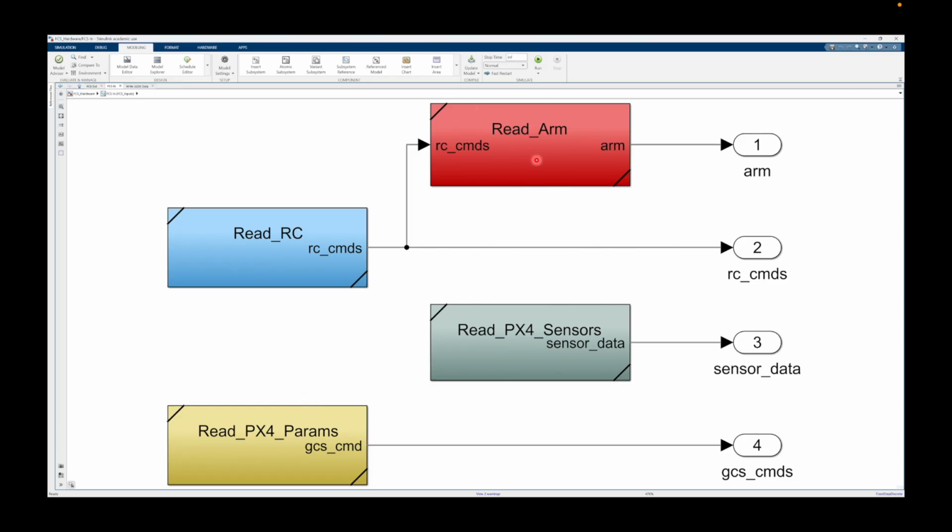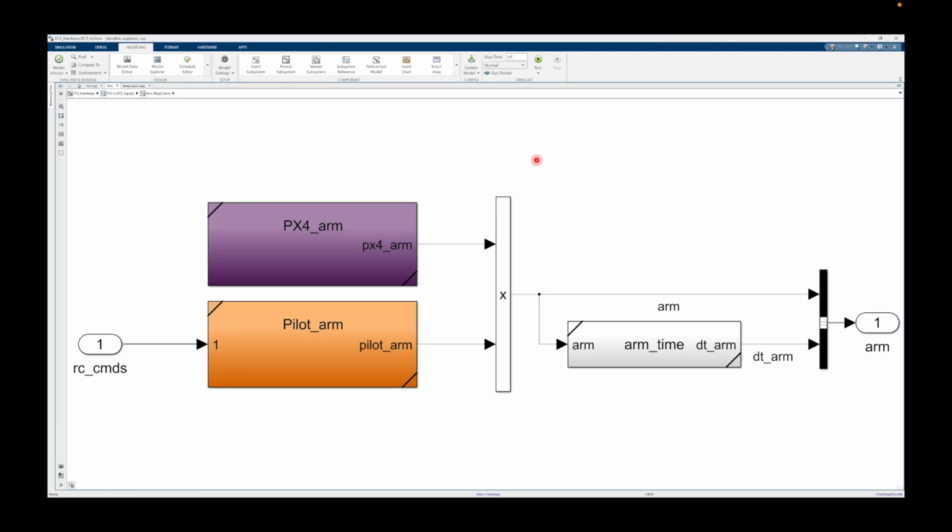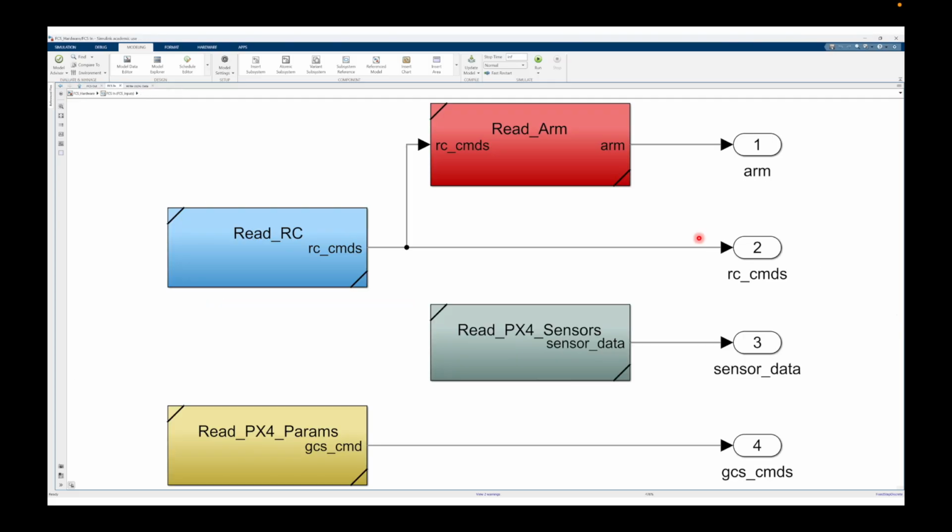So going inside the arming subsystem first, all that's happening is we read in the signal from PX4 ARM, and then we check it against if our pilot switch is turned into the armed position. All that means is that we both want the actual state of the vehicle from PX4 to be armed and for our arm switch to be set correctly in here, and then the arm signal will go out throughout the subsystem. This is for safety, just so that we don't have an ARM switch set inside our Simulink logic that differs from PX4 logic, and we don't have an issue that would normally stop the vehicle from arming be ignored by our logic. So this just reads in the PX4 signal so that there aren't any issues with that.